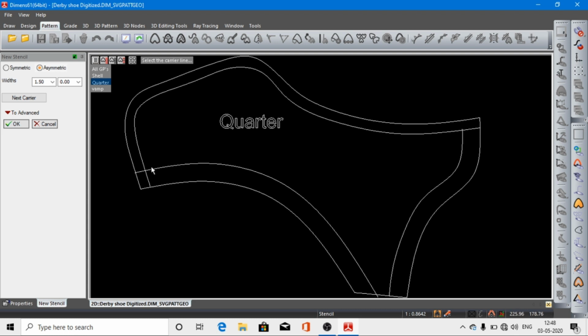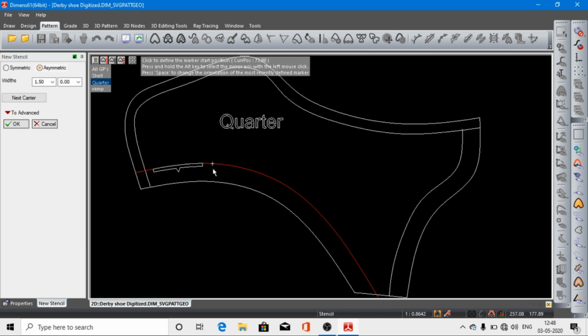First of all, you put the stencil in the underlay place, like this, left click, and then you provide a gap of 1 centimeter at least, or 5 mm, and then again left click, and then okay.